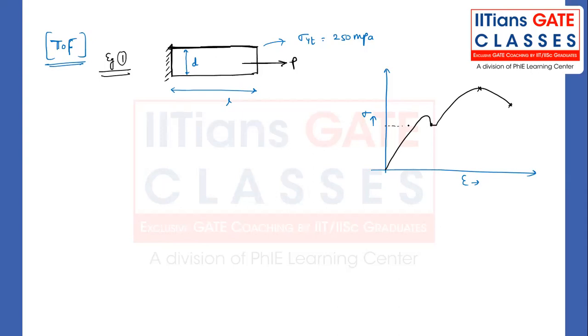So this is what you will be calling the yield strength. This will be your ultimate strength. You need not bother so much about this curve, I'm just telling you for understanding purposes. And this is the failure stress. This is a typical stress versus strain diagram for mild steel, or you can say a ductile material. If it is reaching beyond this yield point, point A, we consider this as a failure point with respect to strength of materials.